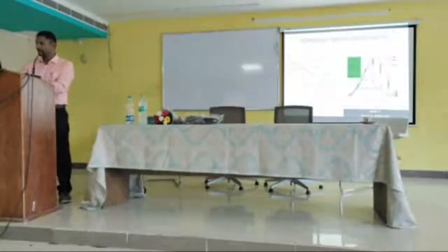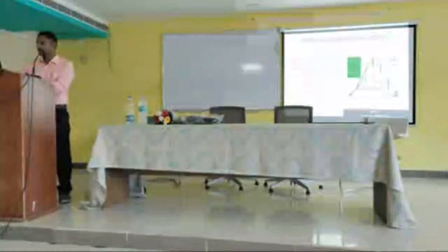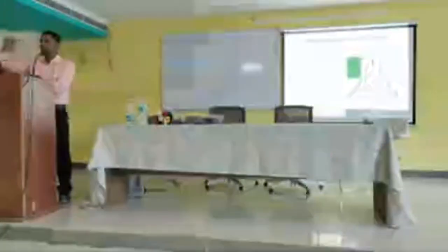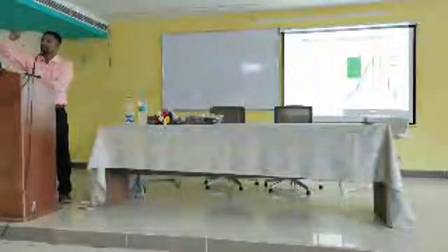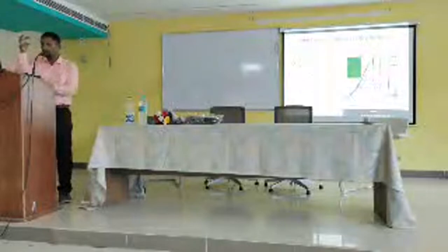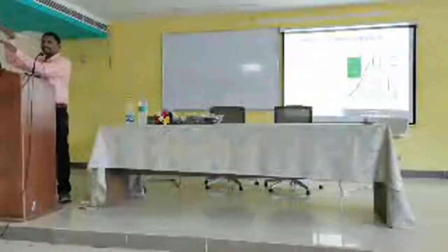Next, you can see here, it is in deeper level. If the salinity level is 0, you get maximum output. As the salinity in the water increases till 100%, because of higher salinity, the refractive index keeps getting higher. Because of the higher refractive index, the propagation velocity of the light signal is reduced. So in my sensor, the intensity is minimized.